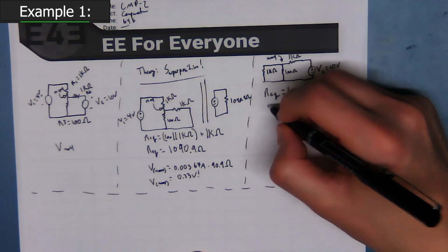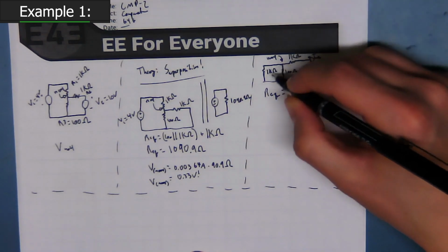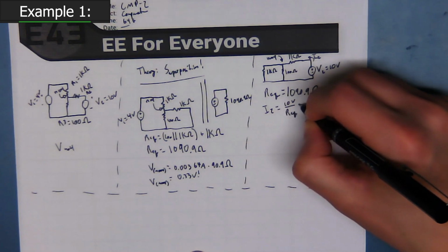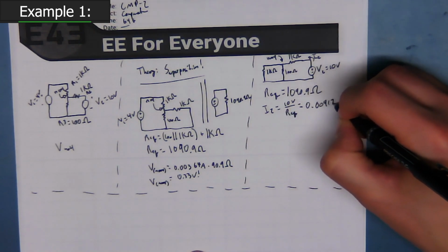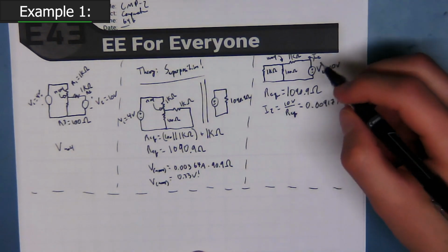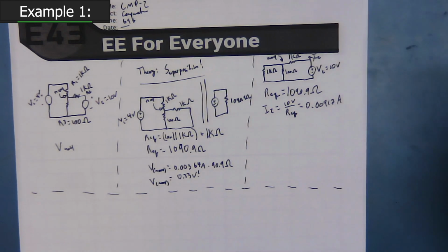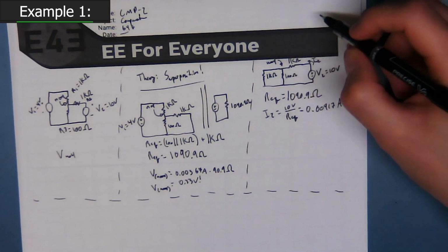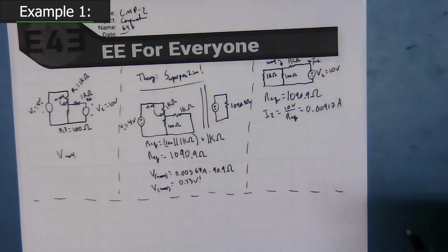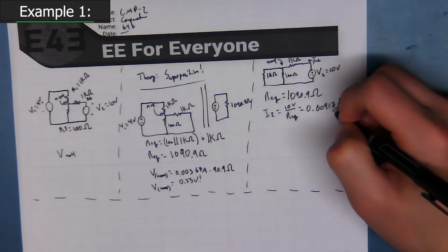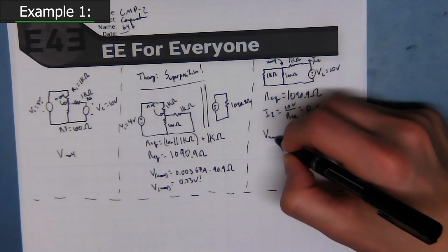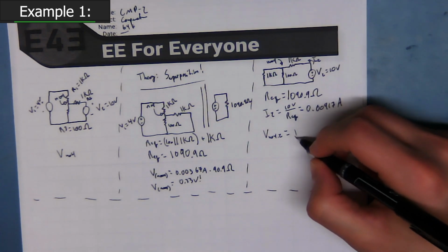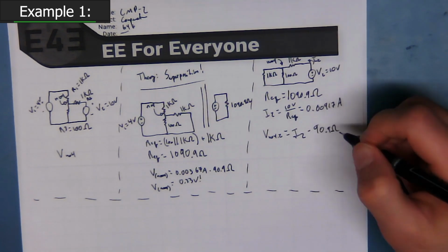So it's the same. And now I2, which is the current flowing out of V2 into that resistor network. Right, we get 10 volts divided by the equivalent resistance. That's basically 9 milliamps. Now we're going to take this and we're going to do the same thing, right? So if we combine these two in parallel, we get 90.9 ohms. If we have one current passing through 90.9 ohms, we know that's the voltage at node 4. Okay? So we're going to do that same exact thing. So this is the second part of that voltage. And we take I2 times 90.9 ohms.